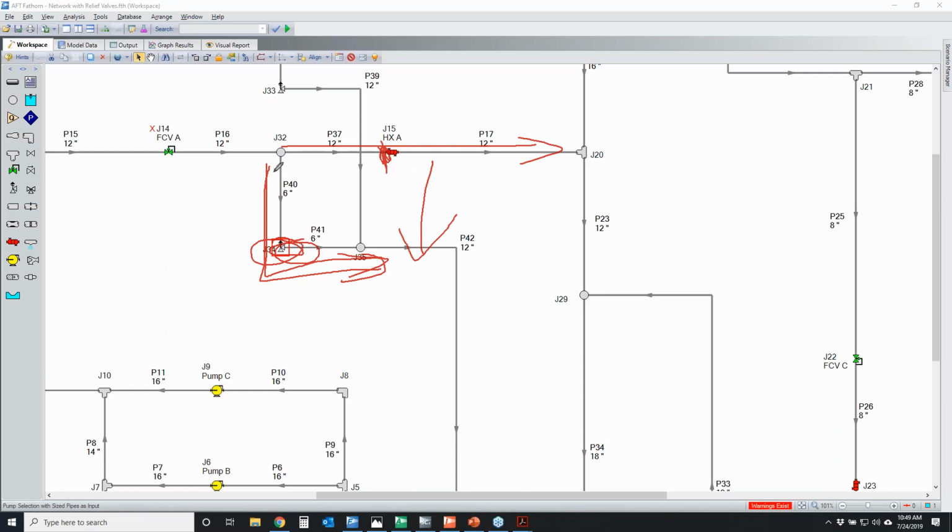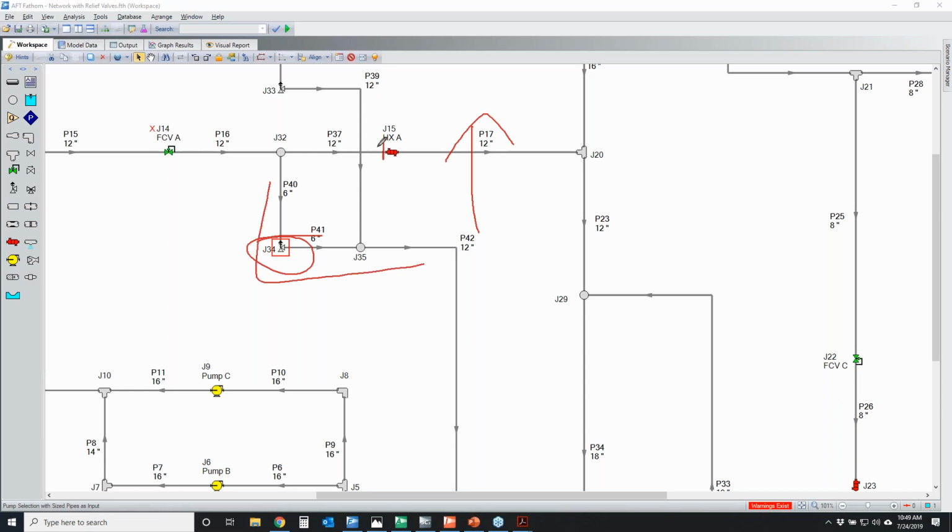When you have flow through this path and through your relief valve such that your pressure drops below the set point, your relief valve closes again. When your relief valve closes, the pressure right here goes back up, causing your relief valve to open again. And when that relief valve is open, you've got flow, and then the pressure here drops, and so the relief valve closes.